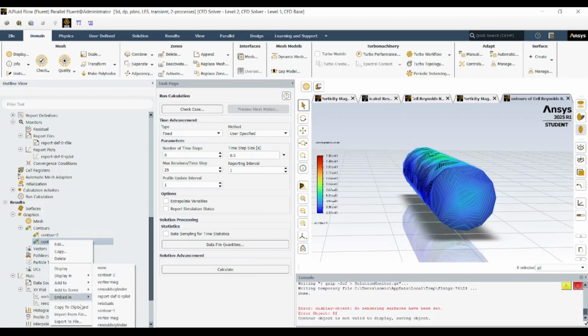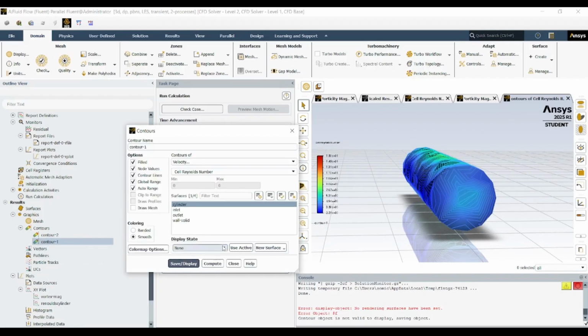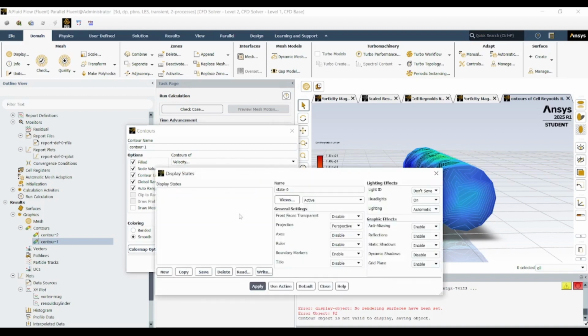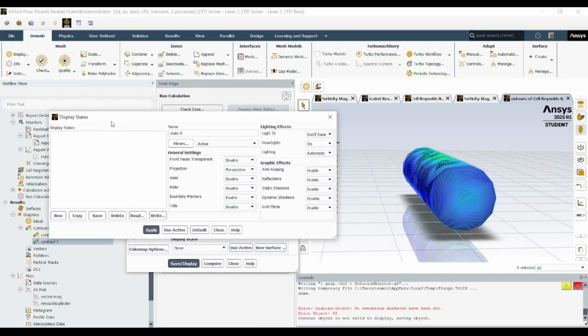Similarly, plotting the surface shear stress helps you understand where the boundary layer separates, a critical point influencing wake formation and drag. These detailed analyses are especially useful for comparing results with analytical correlations, such as those for drag coefficients versus Reynolds numbers from empirical data.